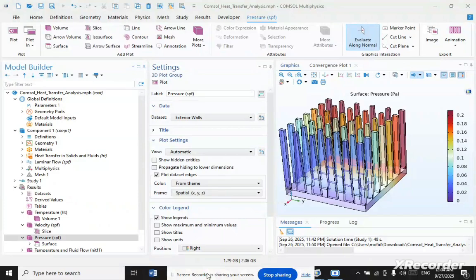Moreover, based on the present work, it was observed that the following points should be considered while designing an effective micropin fin heatsink. The first one is micropin fins with sharp pointed shapes have better heat transfer capabilities compared to a streamlined shape. Further, various innovative pin fin cross sections, like open ring, perform comparatively better than traditional cross sections.